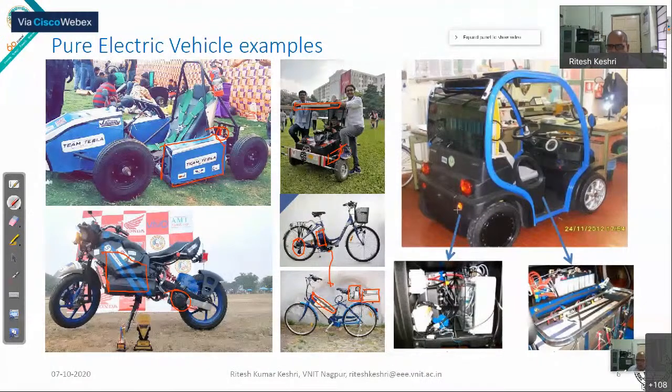And then in this example you can see on top we have a photovoltaic panel, and here we have ultra capacitors. Then we have the battery here, the ultra capacitor and the battery. So here you see that three multiple sources are available, and there are some power electronic arrangements: a bidirectional DC to DC converter for the ultra capacitor, and a unidirectional DC to DC boost converter for the photovoltaic panel. All are here.